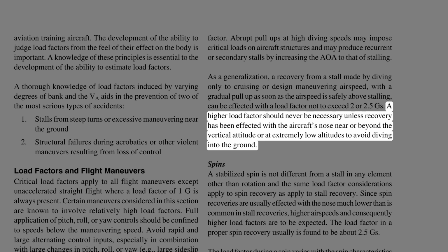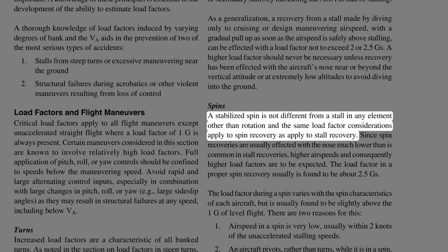A higher load factor should never be necessary unless recovery has been effected with the aircraft's nose near or beyond the vertical attitude or at extremely low altitudes to avoid diving into the ground. Spins. A stabilized spin is not different from a stall in any element other than rotation, and the same load factor considerations apply to spin recovery as apply to stall recovery.